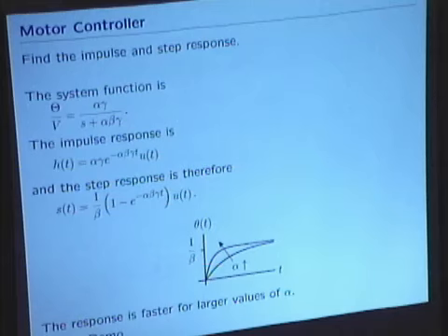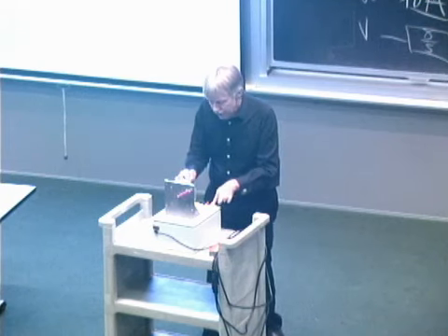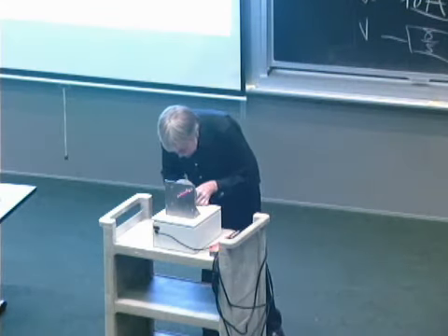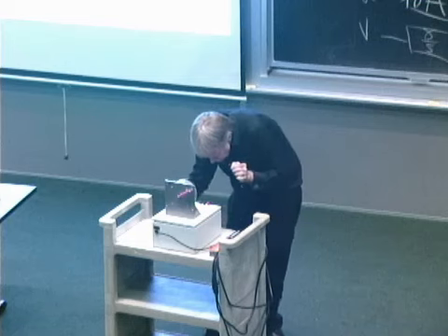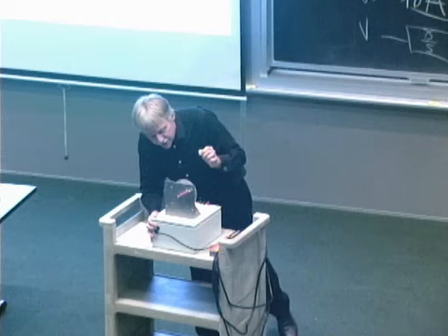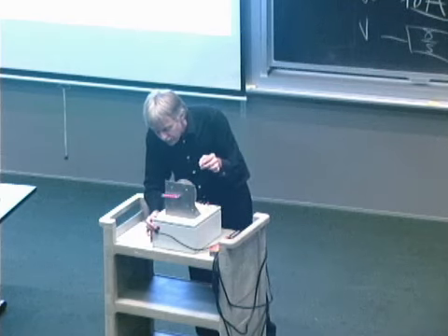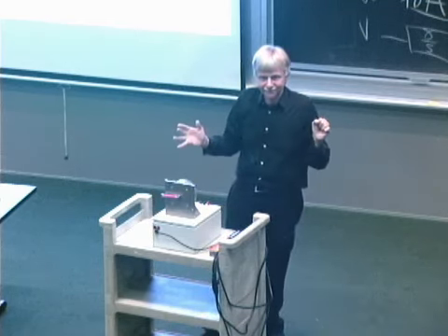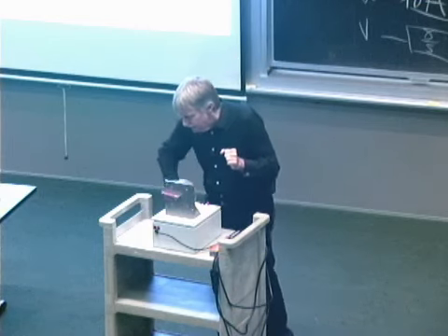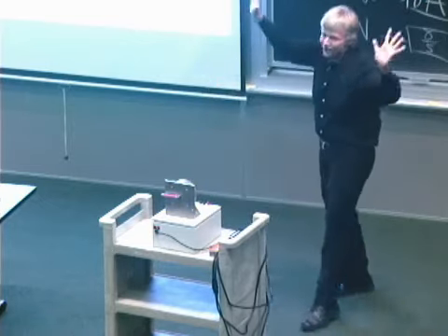So I have to move the input to the amplifier from my pot to the op-amp, which is there, hopefully. So now when I turn it on, it becomes a position controller, okay? And I can test that by turning the pot. And in fact, when I turn the pot, the motor moves. Wonderful, voila, I won, right?